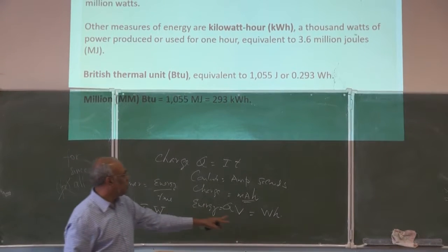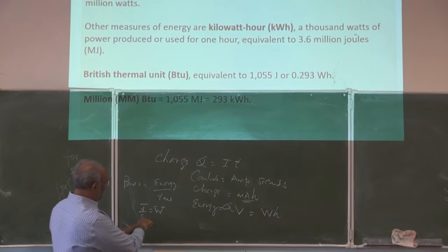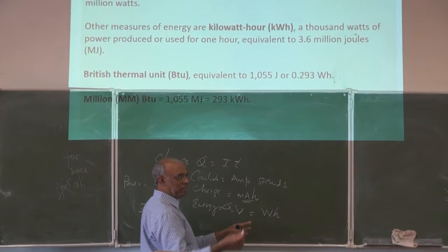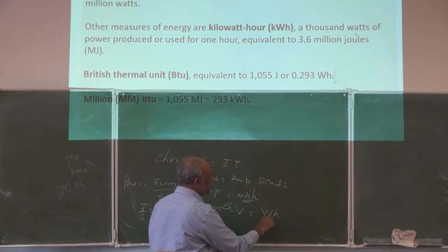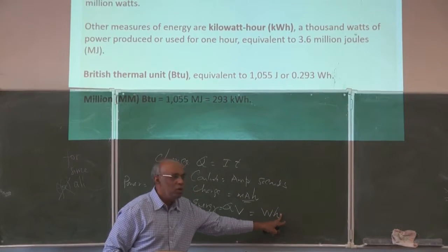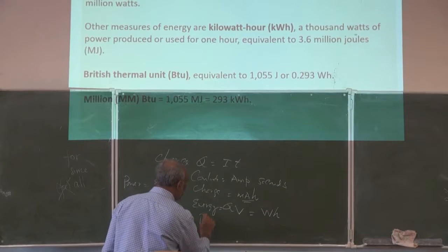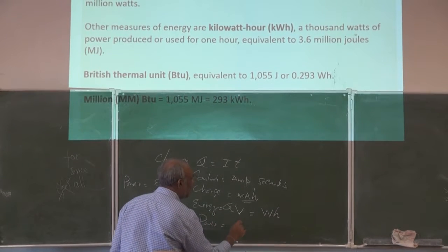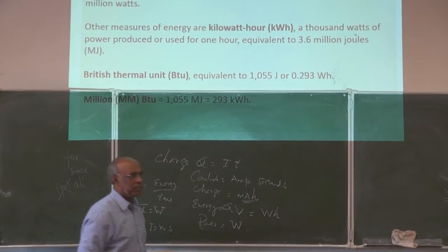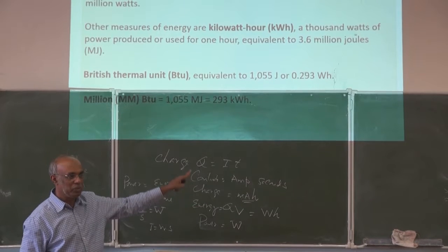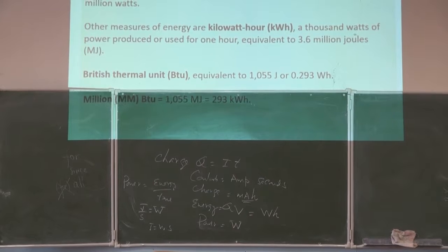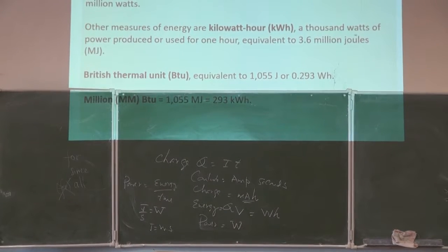That means joule is watt times second. But in battery language, most of the time energy is written as watt hour. It's like watt times second, but you will see watt hour. Then if you want power, mostly you are talking about simply watts. So please remember this. It will come throughout the talk; it's not a very familiar unit, right? That's why I wanted to put this in.